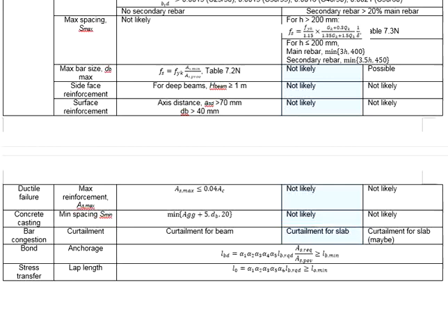Now if you are not confident, you might as well not do the curtailment for the staircase. You will just use slightly more materials, which may not seem necessary. Since you are not confident, to be safe, you don't do the curtailment. This brings up another point.